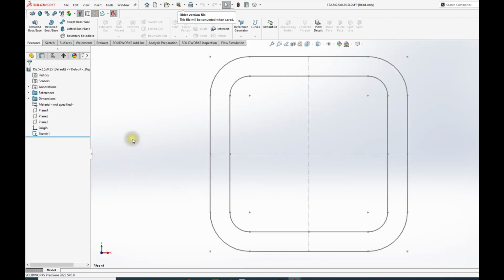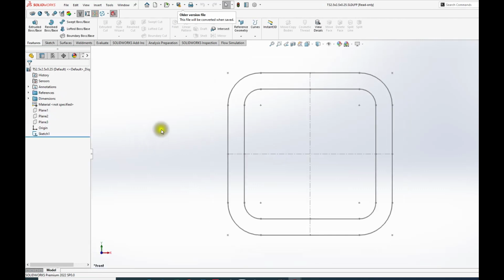Now here's the story. One thing that I want to stress is the fact that this has this handle here. If you modify something that doesn't have those handles, then it's going to be hard to properly accommodate this curve within your weldment design. I think that in my first video I missed those handles, and this is the second video just to improve on that one. They need to have those handles, and obviously this profile had them.